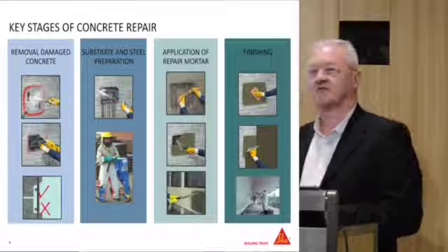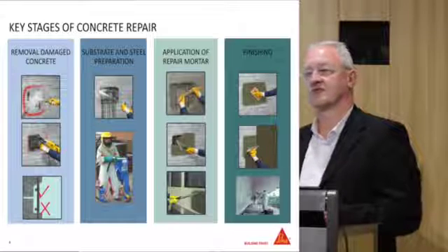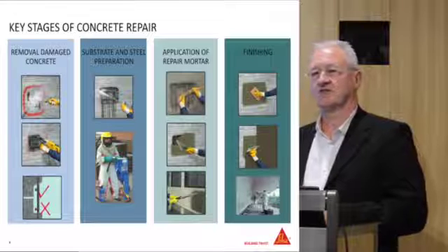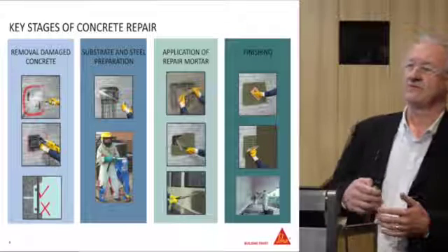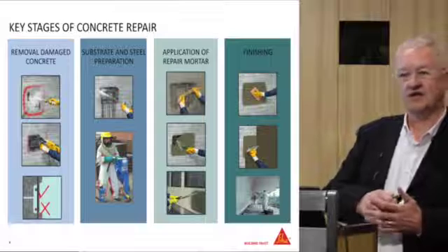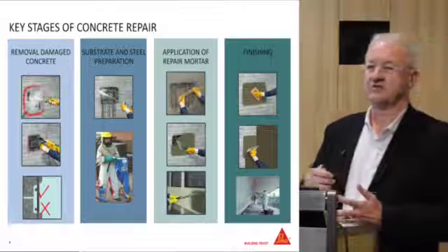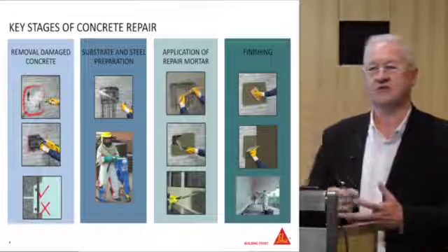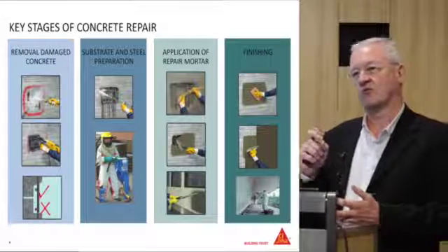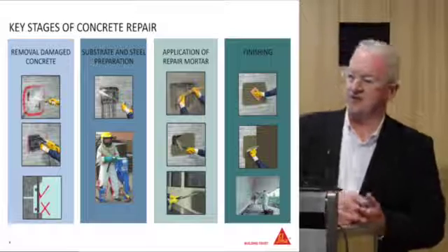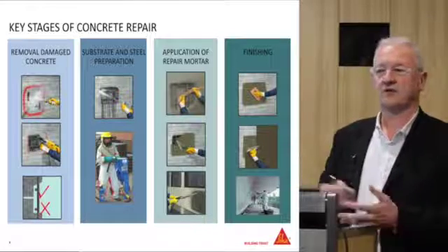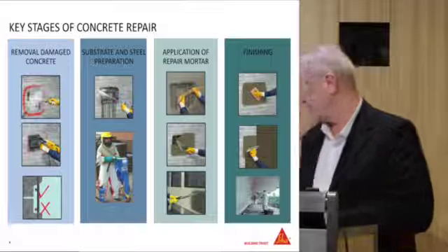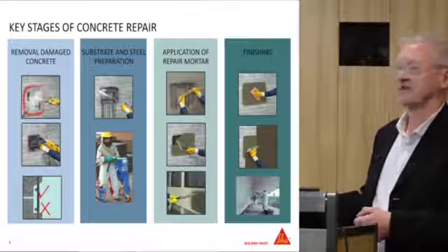A lot of the time, to aesthetically upgrade structures, they tend to be coated, and to get a good coating finish, you normally apply what we call a sealer coat of cementitious product, which just fills the holidays in the concrete or the pores, or you put a thickness of about 1 or 2 millimeters, which gives you a really nice finish to apply the coating. And then it's just a case of applying the coating for the job.